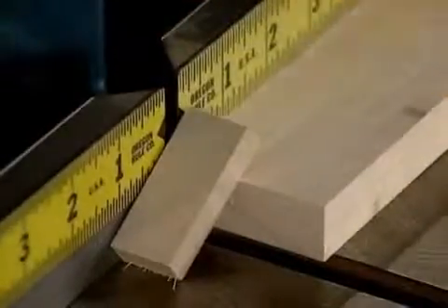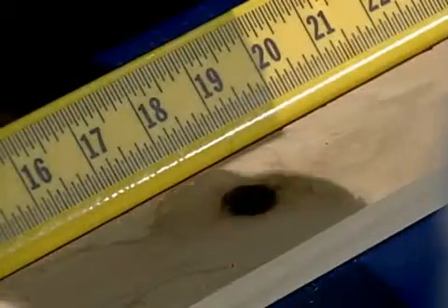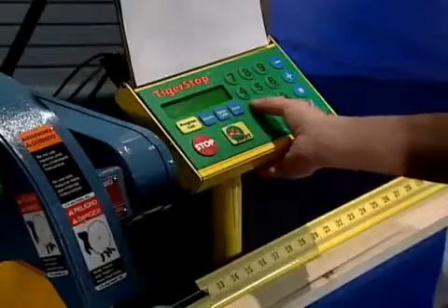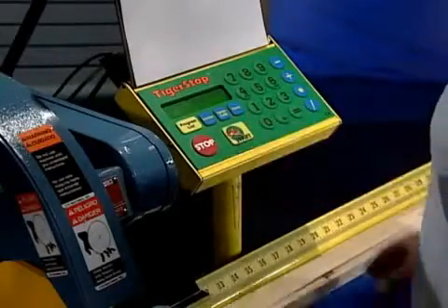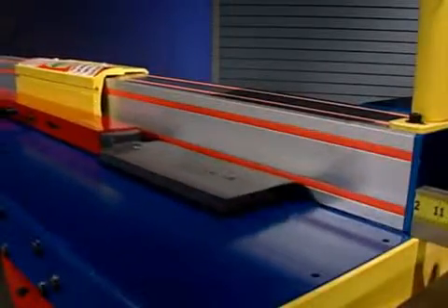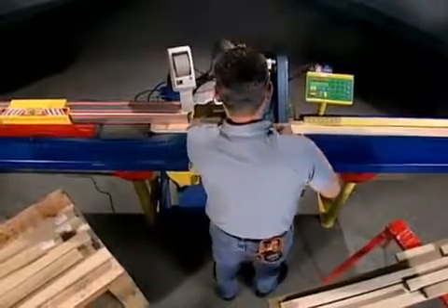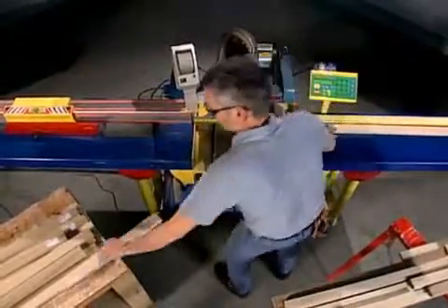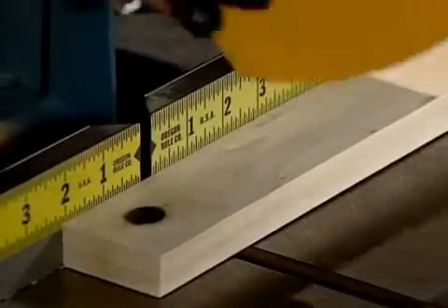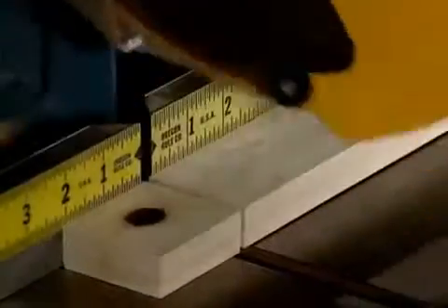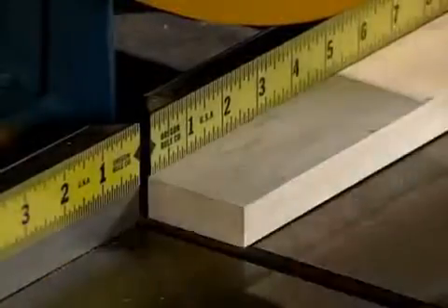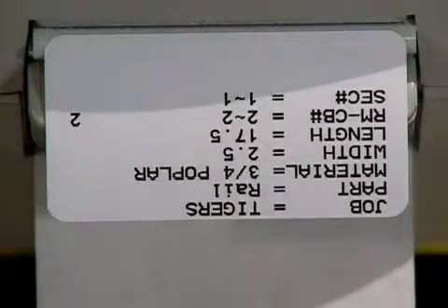Ed's made a trim cut at the beginning of the board. The usable length between the trim and the first defect is 18 inches. Ed enters this length into the controller, and the Optimizer will now look for the right combination of parts to make from the cut list. The TigerStop Optimizer is unparalleled in processing capability, able to effectively consider up to 15,000 different combinations a second for each usable length. While Ed is cutting, a labeler creates a unique label for each piece.